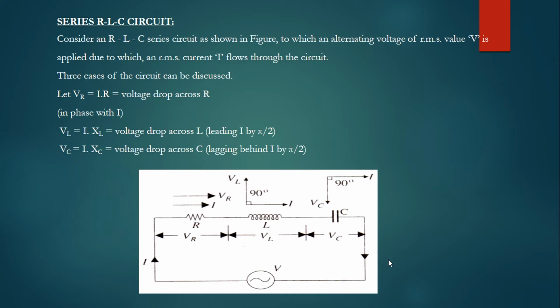Because through resistance, in a pure resistive circuit, current is in phase with voltage, no difference. But when inductance and capacitance come in, current will be lagging or leading. Here both inductance and capacitance are present along with resistance. So it depends upon the value of inductive reactance or capacitive reactance, which decides whether the current is lagging or leading. So once again, when alternating voltage V equal to Vm sin omega t is applied to the circuit, current starts flowing in the circuit.